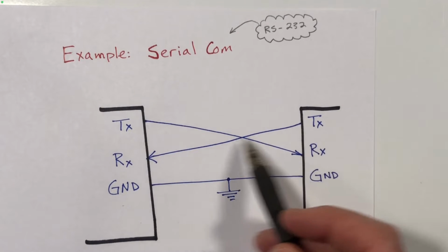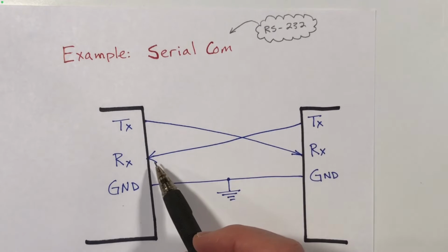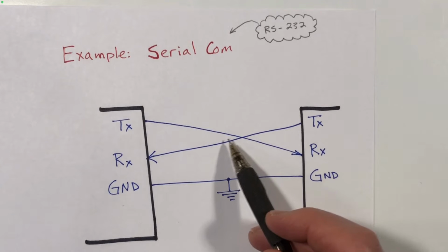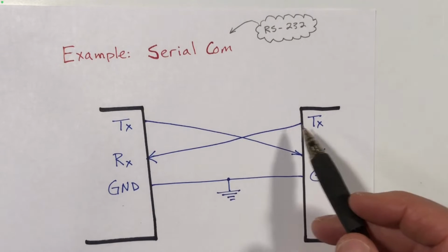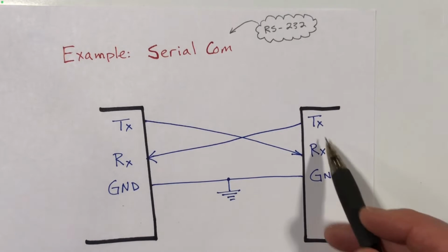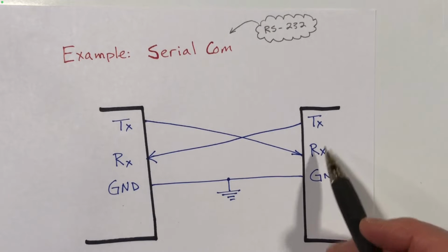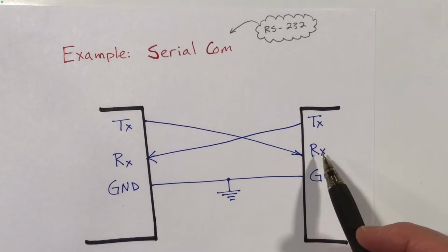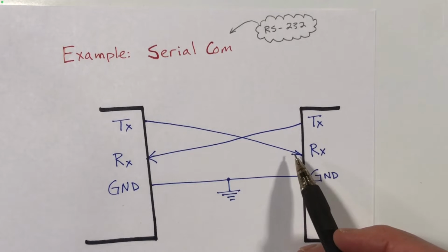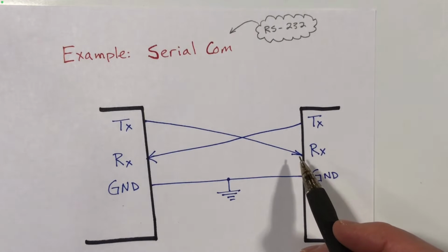The communication channels send 1 byte at a time, and since this is a single wire, each bit has to be sent individually. The two transmission pathways are independent. So the transmit circuit and the receive circuit are independent. Well, they may share a system clock or something like that, but you can be transmitting simultaneously in both directions. And in that sense, it's said to be full duplex.